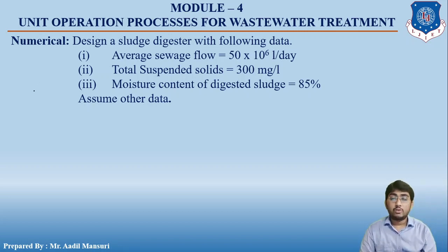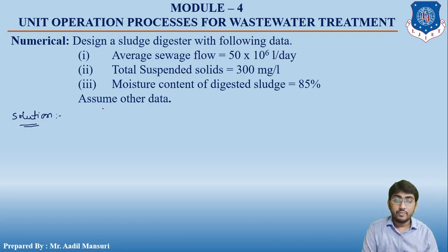Okay, so let us now start with the solution. First thing we need to find out is the mass of suspended solids. We know that total suspended solid is 300 milligram per liter and total quantity of wastewater is 50 million liters, right?